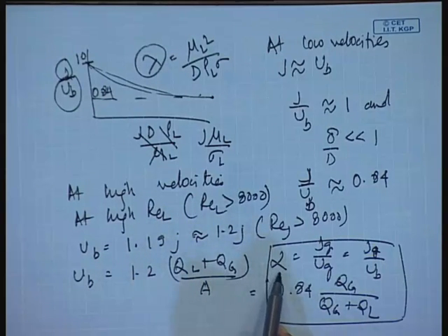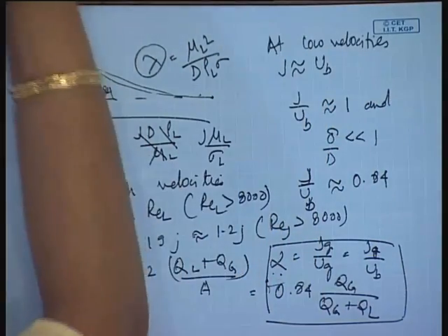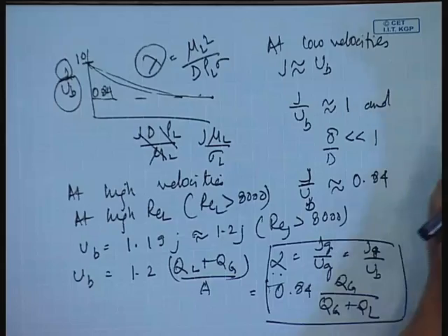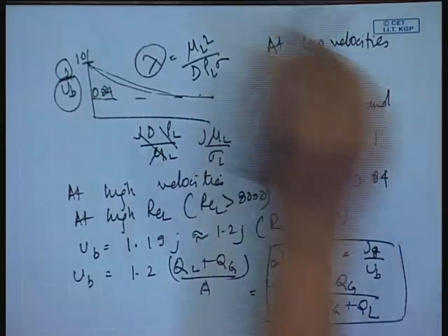If this is substituted in the expression of alpha, we find that alpha can be obtained by this particular expression. Now, if this alpha is substituted into the pressure gradient expression, then we can get the accurate pressure gradient expression. But remember, this pressure gradient is not very simple. Why? Because it primarily comprises the frictional pressure gradient, it does not comprise anything else.